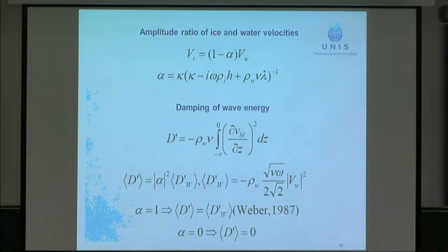Again, talking about the eddy parameter, which is a crucial factor in your analysis, you compute it by averaging the Reynolds stresses. You take only two components. I wonder if the other components are not important, or maybe it has to do with your method of measuring the Reynolds stresses using an acoustical device instead of using a wire, with which you can really measure all nine components. I measure 3 components of velocity. Yeah, but how about the other two? I mean, the vertical motion. I measure vertical and 2 horizontal.